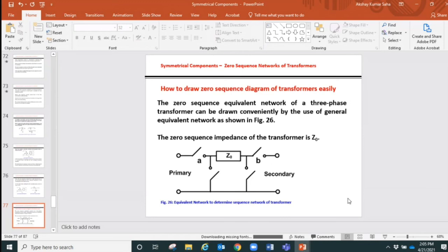But for the synchronous machine, we saw the positive sequence impedance is different and it depends on the time duration of interest. If it is subtransient, we use subtransient reactance. If it is transient, we use transient reactance. If it is steady state, we use steady state reactance. The negative sequence impedance is completely different. It uses the average of Xd and Xq, so (Xd + Xq)/2. So that's the negative sequence.